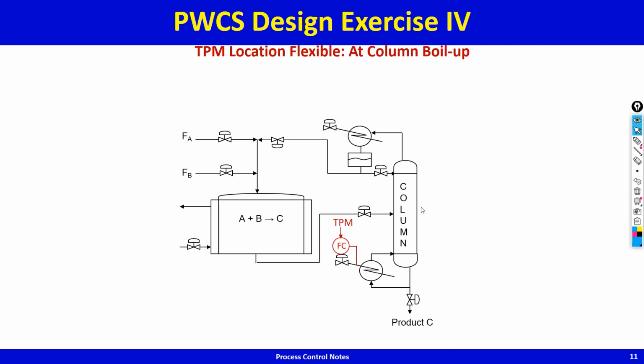Your distillate starts becoming impure, your bottom starts becoming impure, and this entrainment flooding is because of too high a vapor rate, and that will be reflected as a large pressure drop across the column.